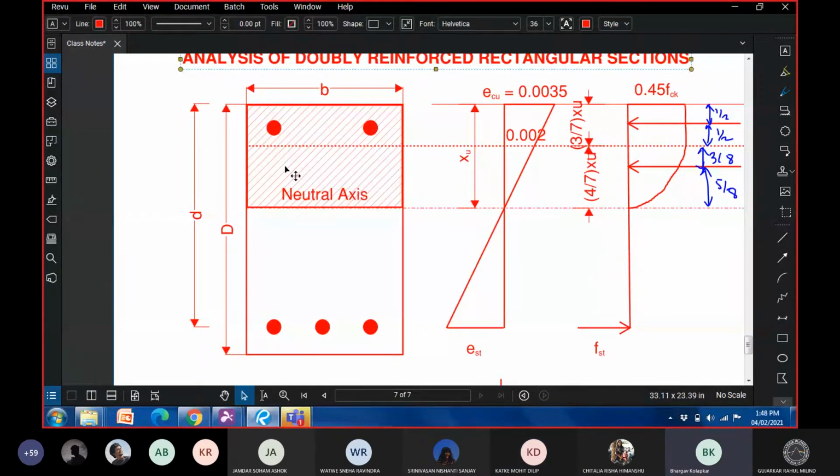Like I said in the last lecture, when the depth of the beam that is being provided is not sufficient to carry the load, we always have an option of providing reinforcement even in the compression zone. What happens because of that is the moment of resistance of the beam increases while the beam is still under reinforced. Yes, there are a lot of calculations behind how much to put and where to put, and we are going to get into these calculations in a while. Please write down.